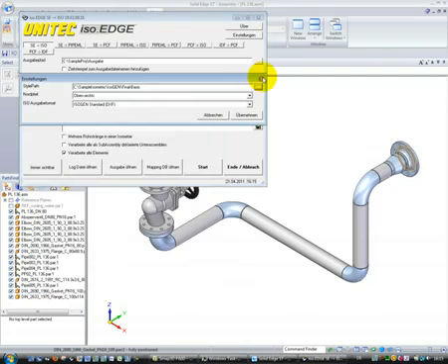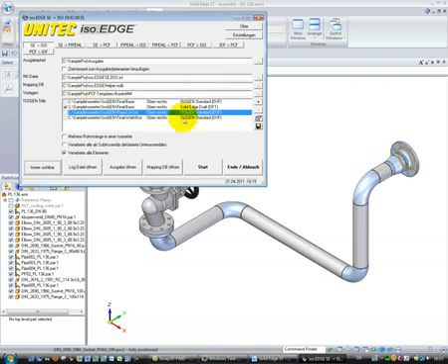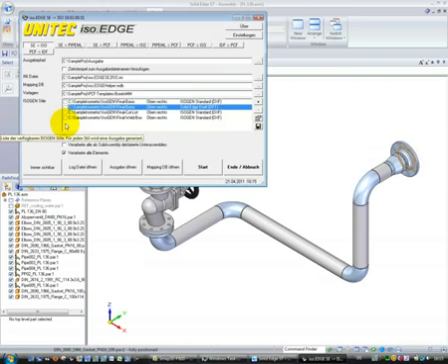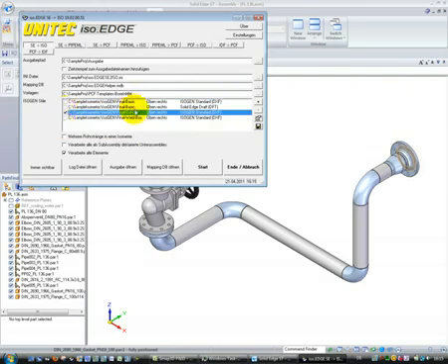And normally if a user works with this application, then in this list the required styles are prepared, and the user just has to select with which style he would like to create a drawing now. In our sample we would like to create a cut list drawing, so I select this entry here, I save it, and then I have some settings for which content I would like to have in such a drawing, more pipelines in one isometric or some similar settings.